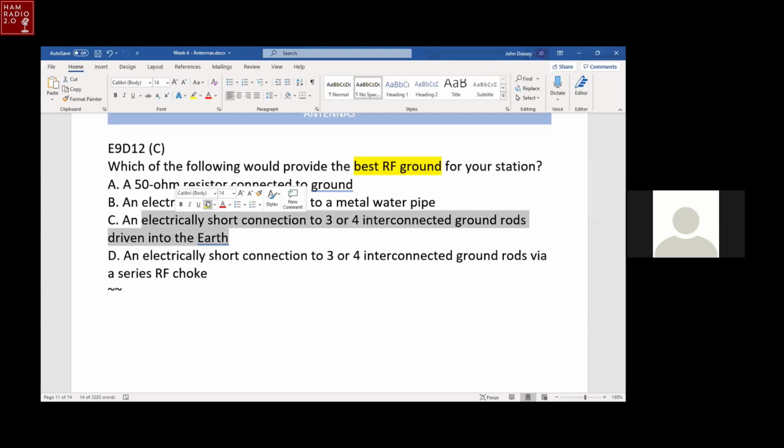ground. And where I've got my ground rods sitting, I think I've got 3 that I've got the 6-gauge wire connecting to, and then the wire coming through the wall connects to the middle one. And they're all driven into the ground in the flower bed, and that flower bed stays wet. So that's a real good low impedance connection for RF.